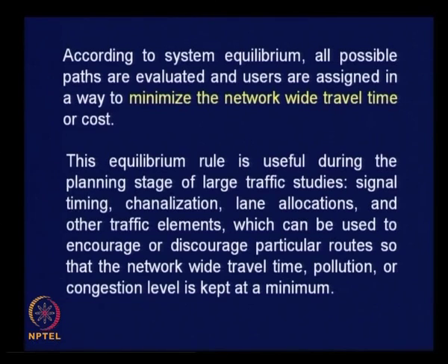This equilibrium rule is useful during the planning stage of large traffic studies, mostly not for transportation system planning, only for traffic studies involving signal timing, channelization exercises, lane allocations and other traffic elements which can be used to encourage or discourage particular routes, so that the network-wide travel time and the resulting pollution or congestion level is kept at minimum.